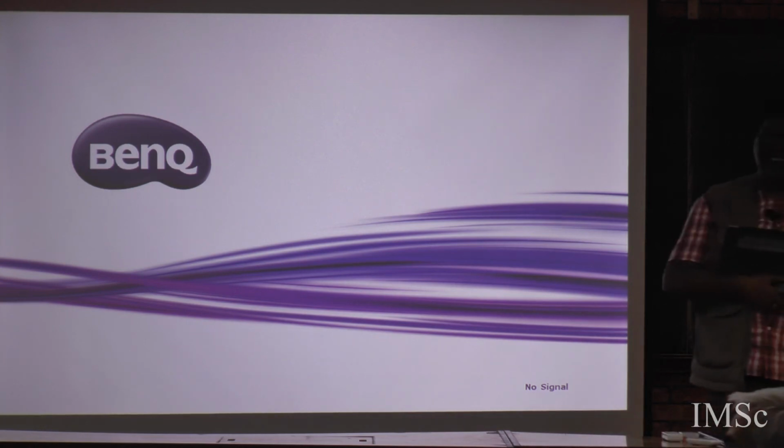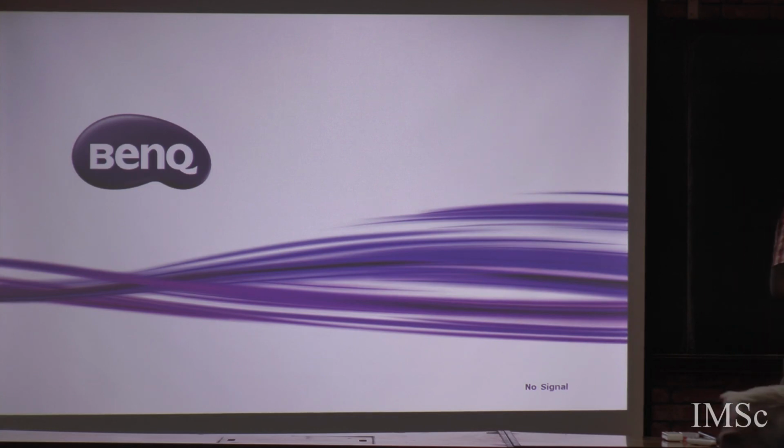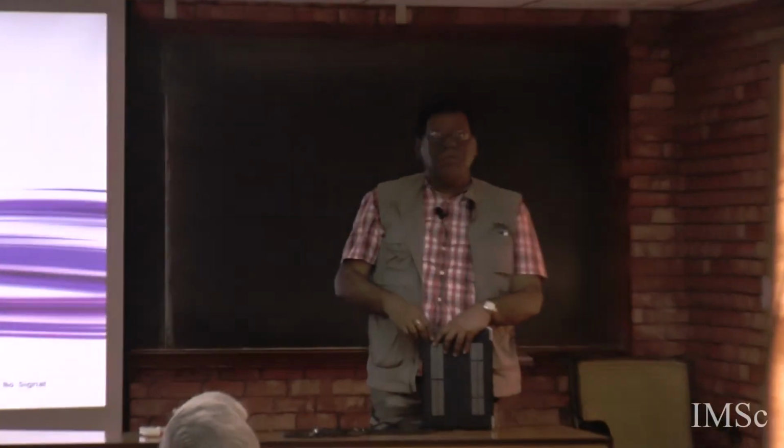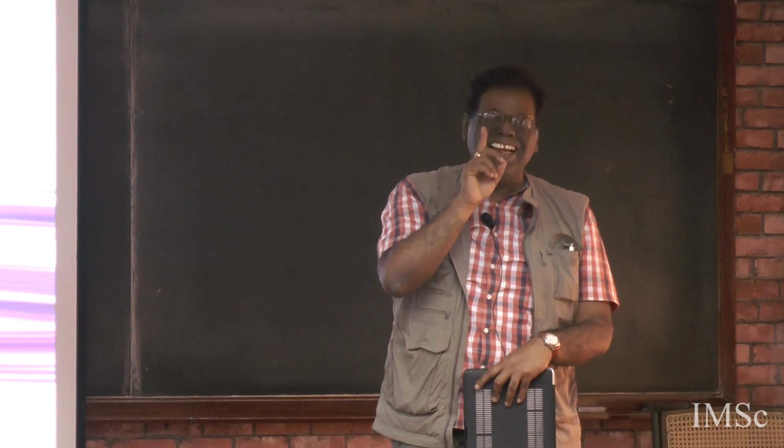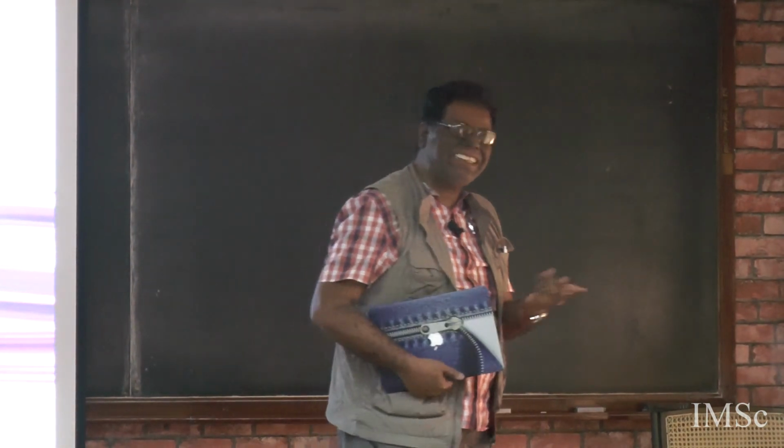Just one more point here. If you are taking a zero temperature solid, then over a long time you will always get stuck if you are below the threshold. In a zero temperature solid, you will never get nucleation and growth. You will get stuck, of course, because you cannot cross the barrier. The statement has been made that it's only a finite temperature effect. I said thermodynamics. Thermodynamics means finite temperature.